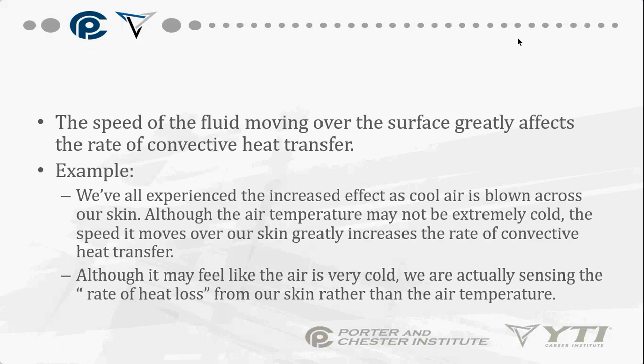So we've all experienced the increased effect when cool air is blown across our skin. Although the air temperature may not be extremely cold, the speed it moves over our skin greatly increases the rate of convective heat transfer, which is why fan speed is important when you're dealing with air conditioning or forced air heating. If I'm moving the air across the body too fast, that person is going to feel, quote-unquote, a draft and, quote-unquote, feel cold.